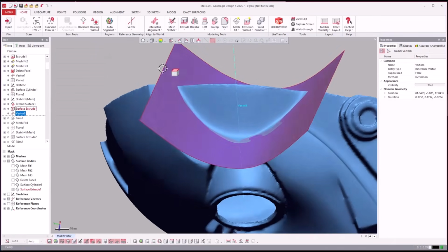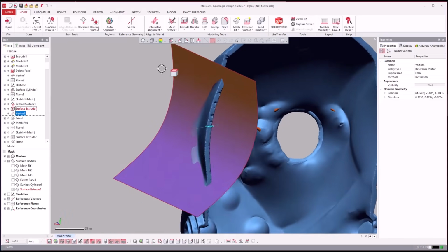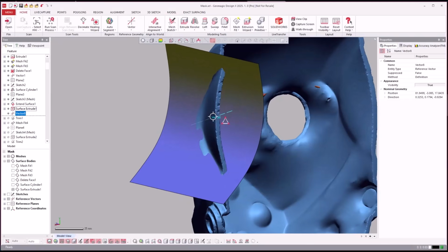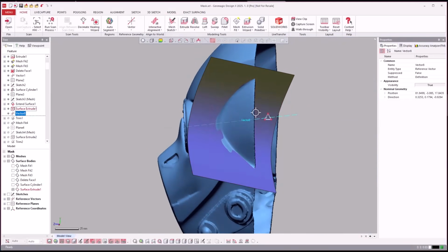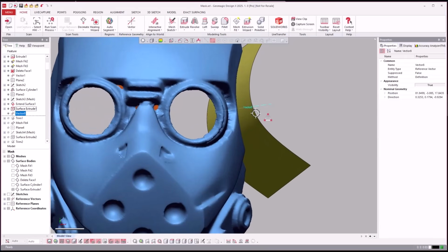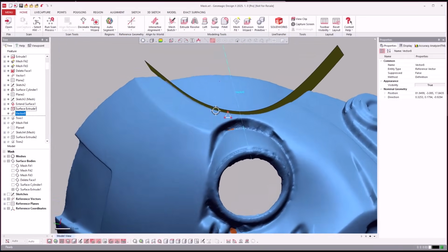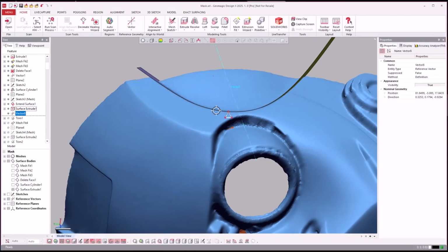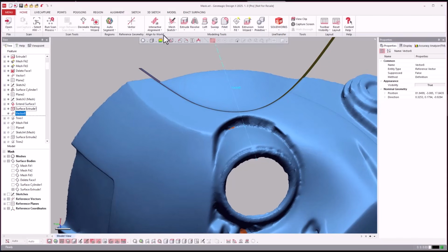Hit OK. And you see what it's doing is it's saying it looks like it's calculated from this direction right there. And then I can intersect a point, create a plane, and then put a plane there and draw the sketch for that. Now for this one, I could even just look, and if visually I can see, yeah, I would really want the extrusion direction to be right here.